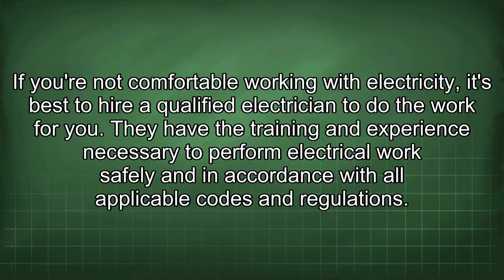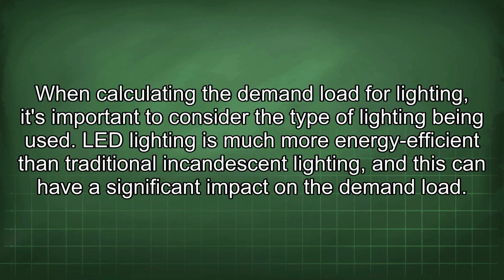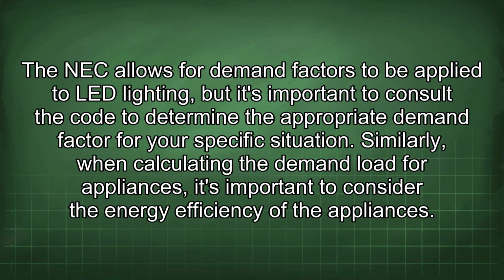When calculating the demand load for lighting, it's important to consider the type of lighting being used. LED lighting is much more energy efficient than traditional incandescent lighting, and this can have a significant impact on the demand load. The NEC allows for demand factors to be applied to LED lighting, but it's important to consult the code to determine the appropriate demand factor for your specific situation.